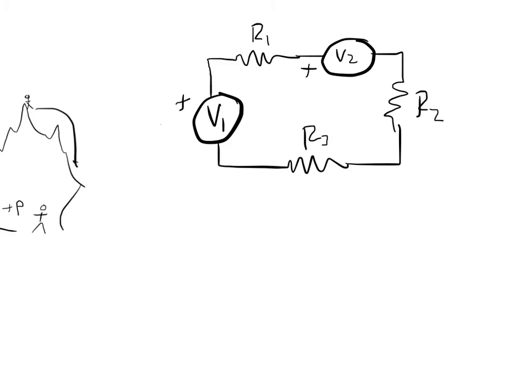If I could put ground somewhere, all that really means is our ground is some reference point we're going to call zero. So we can just pick somewhere and say, well, this is zero. So it's not specified, but that's okay to put that there. But it really doesn't matter because any point we pick to start and going around is going to, once we get back to that original location, then our voltage should all sum to 0.